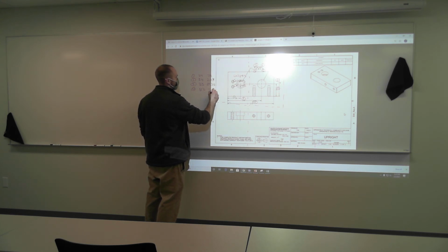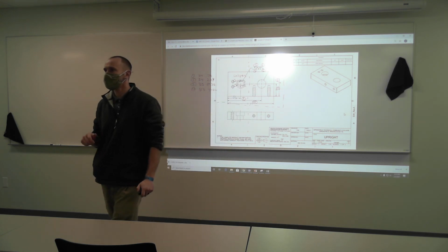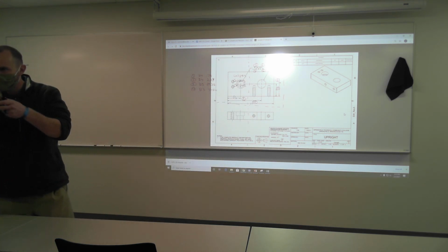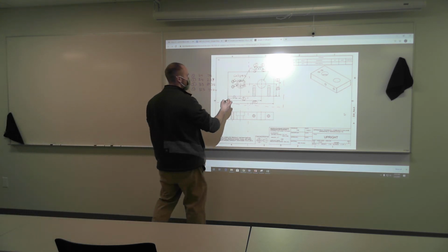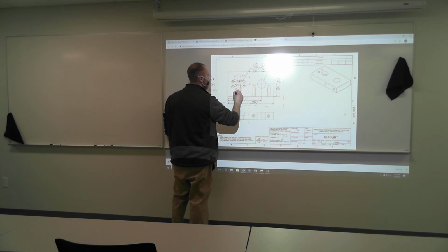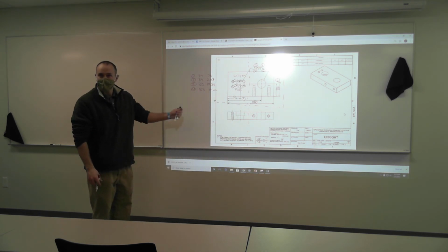Characteristic is through. What gauge would you use? Really, you should use a pin for that. You could say visual as well. You could run your fingernail over it. You'll feel if there's a little drill point in there. The right way to do it is gauge pins. I just write pins for that. And pretty much the rest of this is going to be the same.